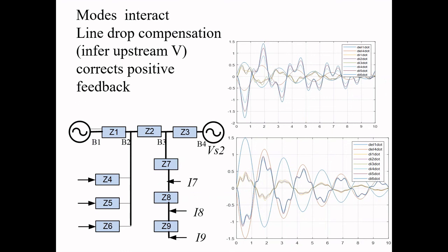My understanding is that Northwest Victoria is fairly weak and the lines have got multiple converters connected along them. So something more like this string that we're talking of here. And what would happen is that the phase lock loops for the different inverters would start to wobble the connection point of 9, which wobbles the connection point of 8, which then creates dynamics of the phase lock loop. So typically, I think 6 to 10 hertz is what has tended to be seen.